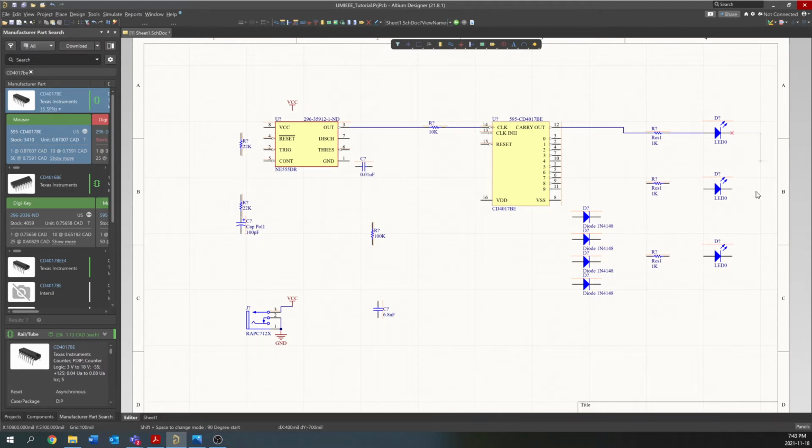We know that the grounds of the diodes are all going to be connected together. When I'm open-ended here and I don't have anything else, you right-click, and that ends your wire, just open to the world. There's nothing connected to it. Eventually, we'll put a ground pin on there, but we won't do that right away.